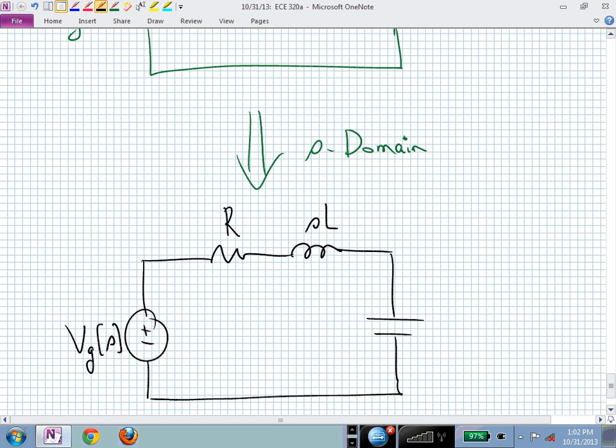That's just SL. And remember, S is a complex number. It's a function of frequency. So instead of, when you were in chapter 9, you were just looking at sinusoidal steady state, and you had an impedance of j omega L. S now can have a real piece. It can be a sigma plus j omega. And that's now multiplying L, and we just collect that into one complex variable S, SL. The impedance of our capacitor, 1 over SC.